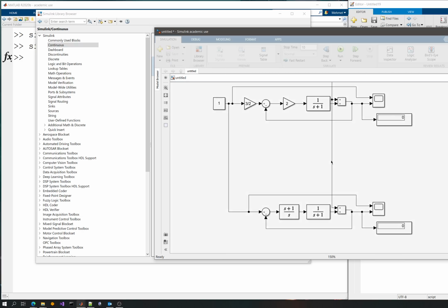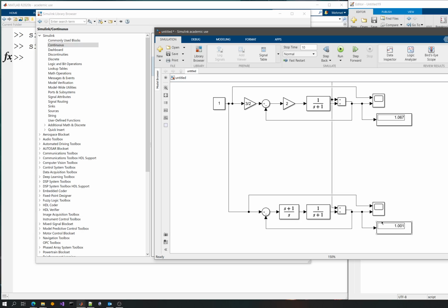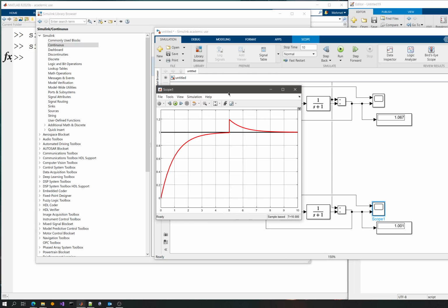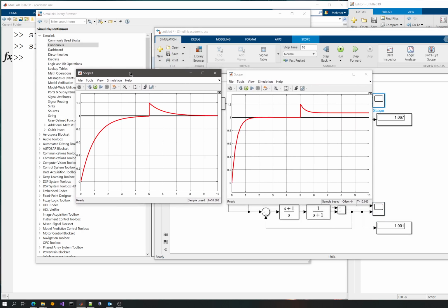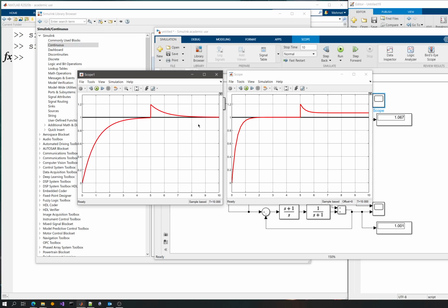Let's hit run here. You can see that there is a big difference in terms of disturbance here. So I have now visualized and compared two controllers. I can also plot them on top of each other, but I can see that the integrator effect takes effect at this point where the P-type controller stops reducing its output. The integrator is still taking the sum, and there is still a difference, and it tries to compensate for that. Maybe it takes a little time, but there's a settling time to the system, so it also will take a certain time for this.